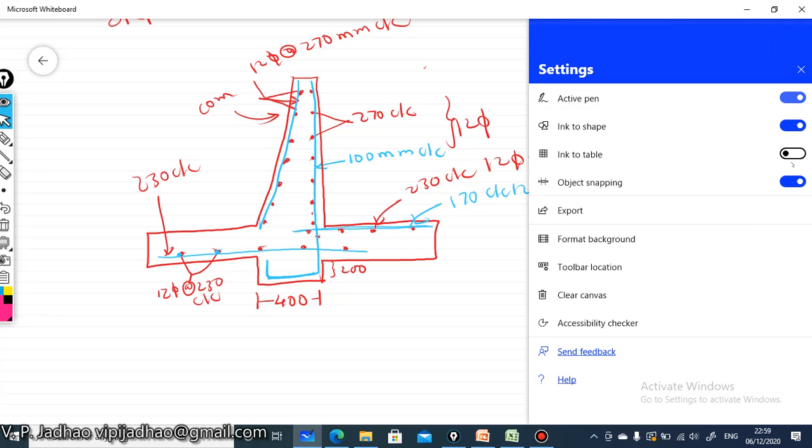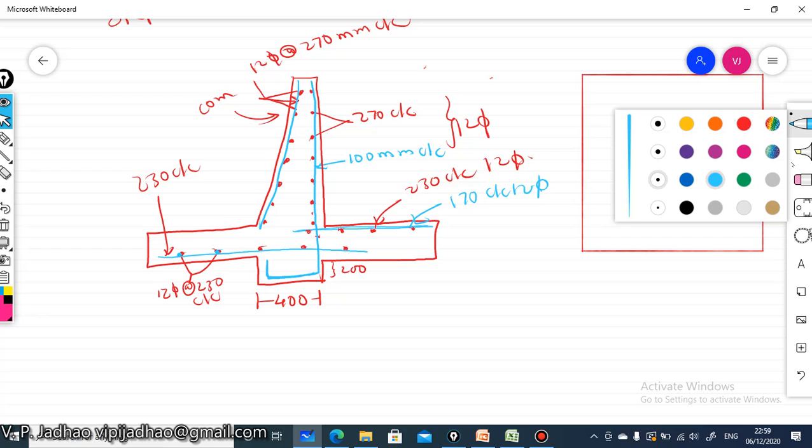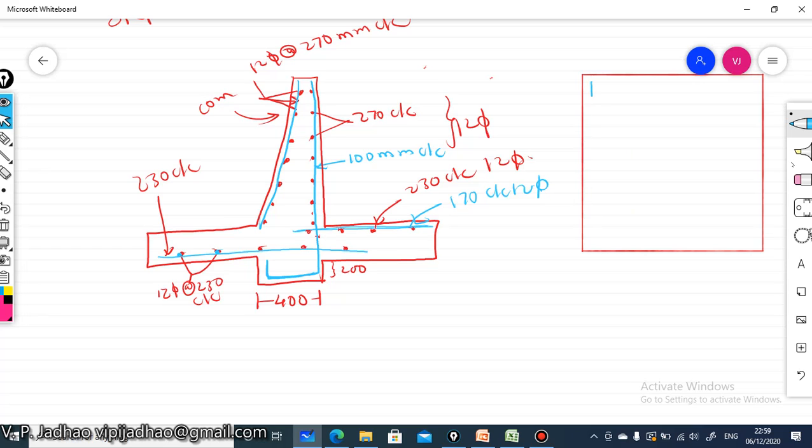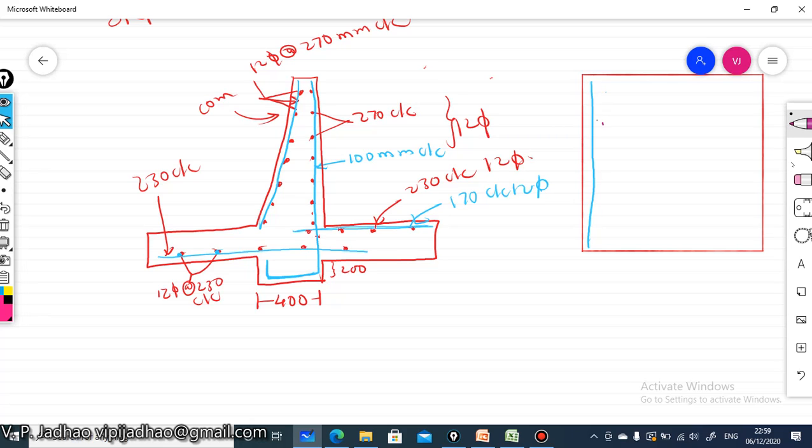And regarding the curtailment, if we see the longitudinal section of this particular retaining wall, then the steel reinforcement that is provided will be something like this. One complete bar at a spacing of 110 mm. Then the second bar will be curtailed from a height of h/3 from the top, like this, and the third bar will be curtailed from a height of 2h/3 from the top.